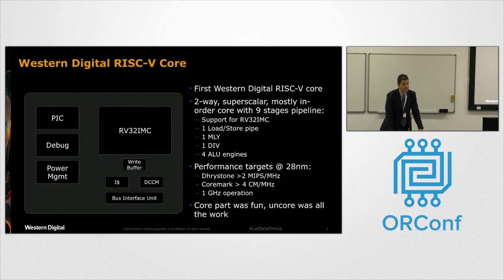The designing of the core, for the very experienced team that I have, with a lot of smart people who came mostly from an Oracle Sun background, was a fun and exciting thing to do. The uncore was a lot of work, because the uncore is really implementing the hardware interfaces like buses, debug and trace, and the platform interrupt controller that had to be defined and negotiated, with somebody developing documentation of what's being implemented. So this uncore part, even on a relatively simple core, generates a tremendous amount of work and meetings and discussions to understand what it really is.